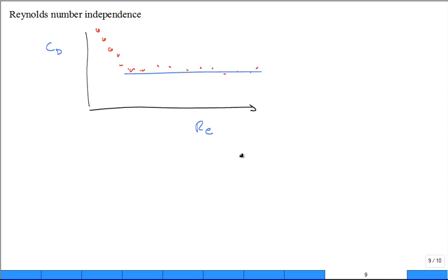And this happens a lot. And so for high Reynolds number flows, the drag coefficient is Reynolds number independent. It doesn't depend on it. All right. Anybody look at, maybe you're an aficionado of new cars, and you're looking at the aerodynamic drag on new cars, and you can go out and look at the drag coefficient for new cars and old cars, and they compare them, pickup trucks and all kinds of cars.